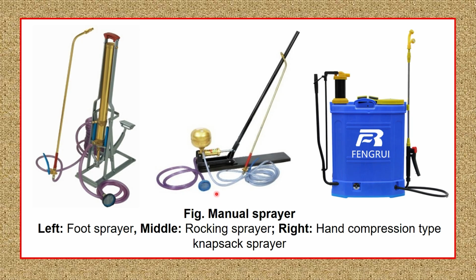But in dryland cultivations, the rocker sprayer or foot sprayers are not much beneficial, because they require more operators, at least two people are required to operate this, one to pressurize the fluid by operating the pump either by foot or by handle, another person to handle this spray gun in the field.